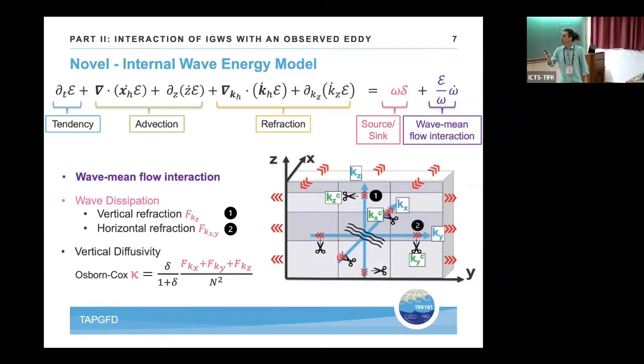Okay? Now we will do simulations solving this equation for one specific area and see how the spectrum of the wave field is evolving. We don't consider any sources of energy, so these are spin-down simulations, and we will consider only one sink of energy, which we relate to wave breaking by wave refraction. And this I try to explain with this sketch here.